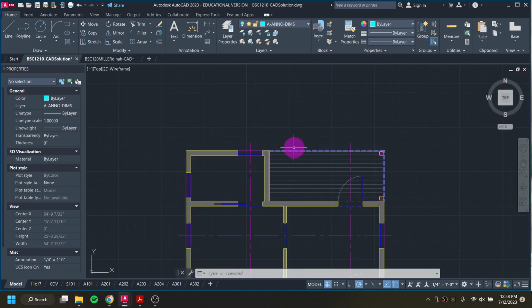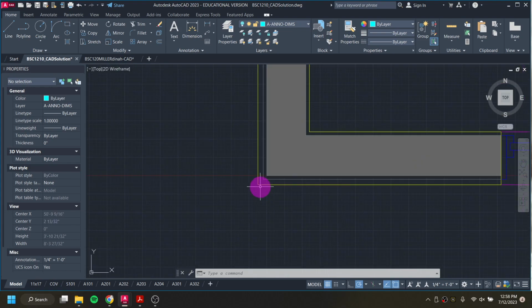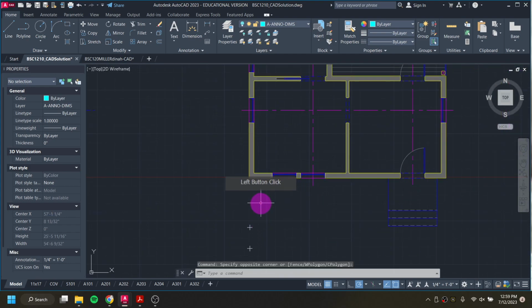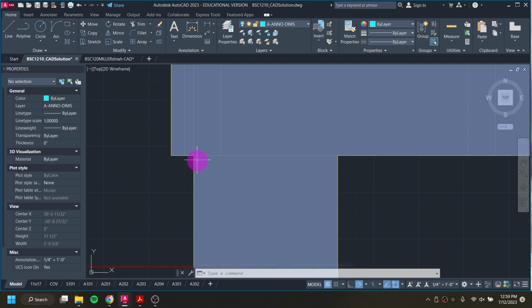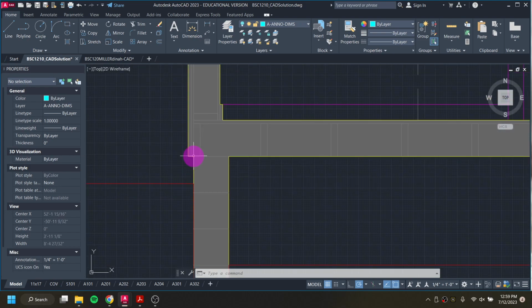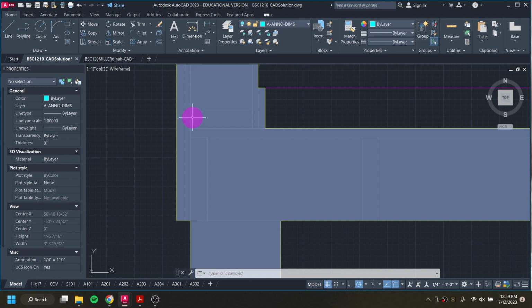So if I was looking at the south elevation, I need to make sure that I'm drawing the elevation with the fact that we are going to have a half an inch out for that plywood sheathing, and then 3/4 inch out for that siding on both sides of this. That 24 feet, and we can especially see it if I zoom in here on the section view, is going to be just from where the foundation sits to where that stud wall sits. That's where the 24 feet is. So we need to make sure we're expanding outwards on either side.